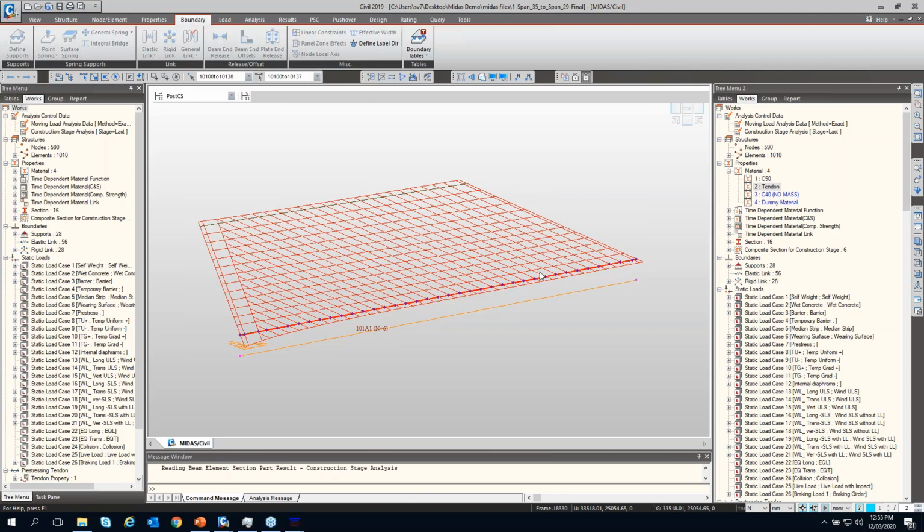What are pre-stress secondary effects? So I'll just try to explain how the pre-stressing is working. When you give a pre-stressing load, you're applying a tendon with some eccentricity, and you're inputting an axial load onto it. You're stressing it, and at a particular section, there is the axial load and the moment which is caused due to the axial load, which is eccentric to the centroid of the section, and it tries to deform the whole girder.